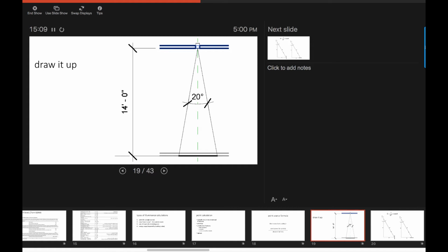I want my mosaic to be much brighter, so I maybe will light it with an additional, say, 3 times as much, 9 or 10 foot candles. Then you just run the numbers on different lamps.